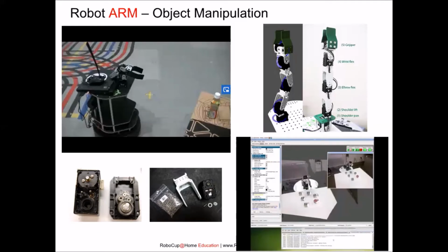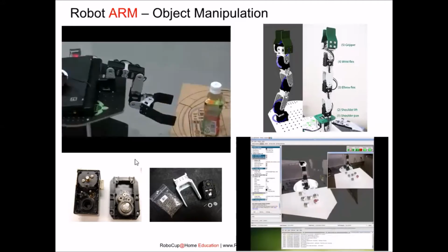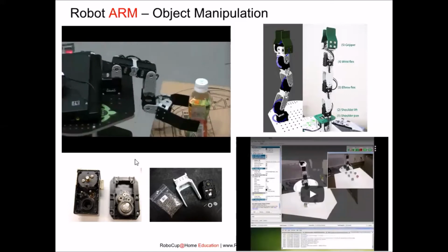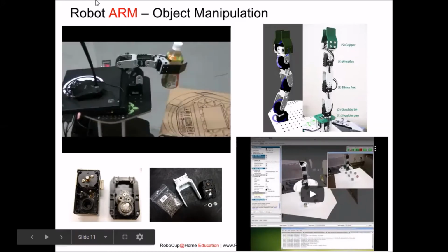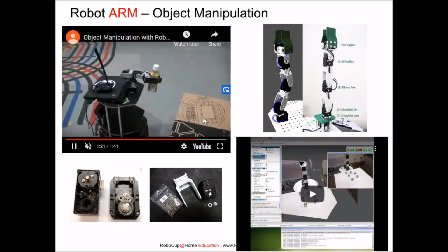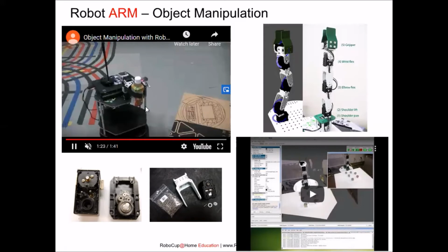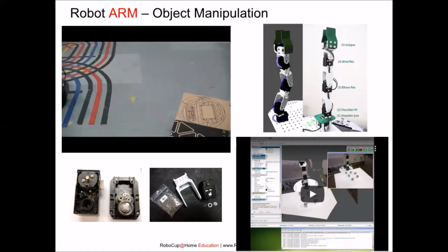Mobile manipulation means the arm is able to move around. So it actually extends the working envelope of the arm, and it's able to grab something outside the boundary it could initially reach, by moving forwards or moving close to the object, over the working envelope of the arm, right? So over here you can see how this robot is able to grab this from a far location. It comes from another point, comes to this point in front, then it starts to detect and align itself. We can see there's actually a sensor down here used to detect this object. So it detects, it aligns itself, then it starts to grab.